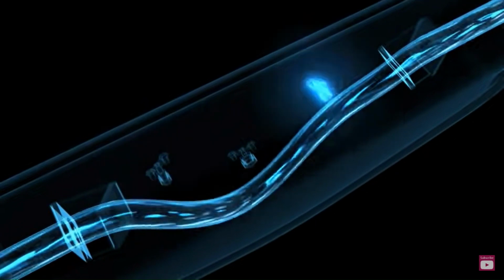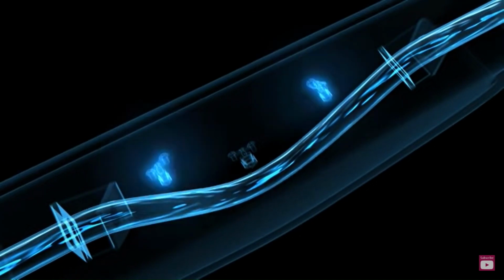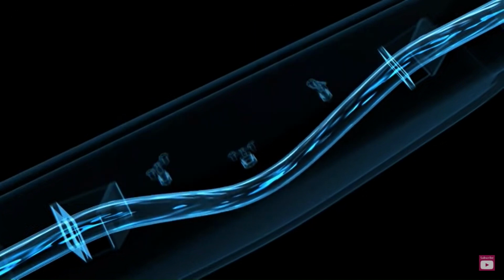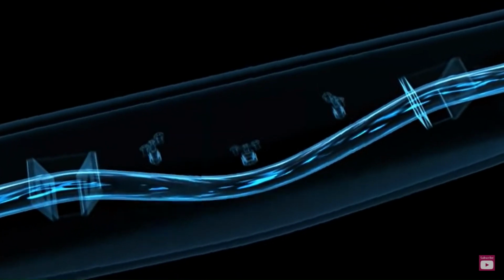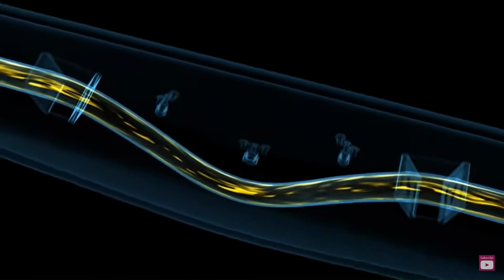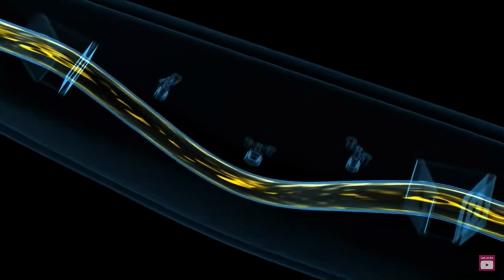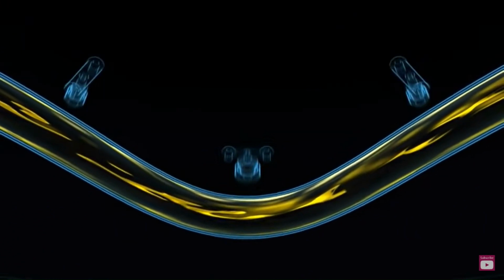The application of the Coriolis measuring principle doesn't stop here. It can also be used to simultaneously determine the density of the flowing fluid. To do so, the sensors also register the oscillating frequency. In other words, how often the measuring tube moves back and forth in 1 second. From the animation, it's clear that a tube filled with water oscillates more frequently than a tube filled with honey, for example, which has a far higher density. Thus, the oscillating frequency is a direct measure of the fluid's density. Both the density and the flow are determined simultaneously but independently via the tube oscillation.